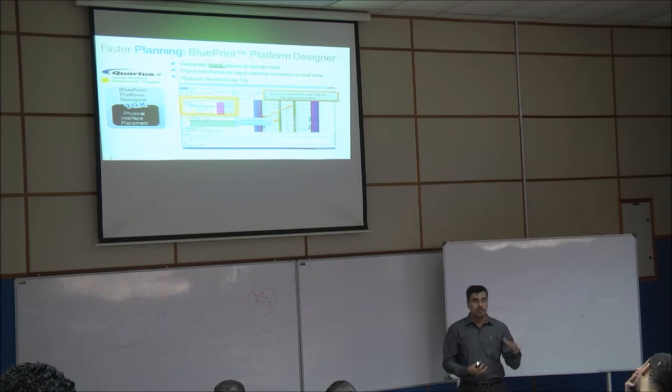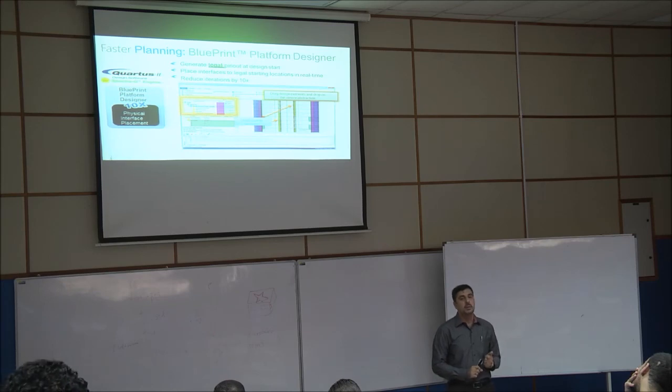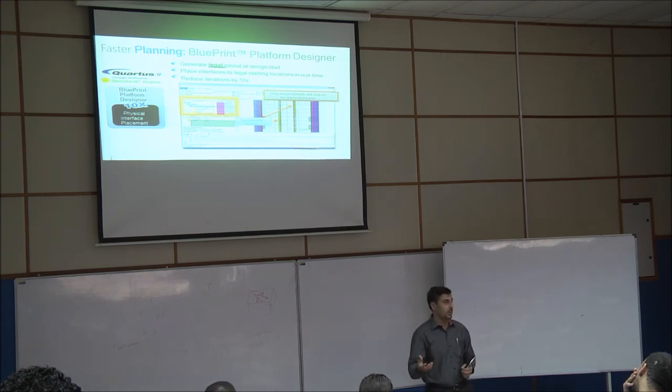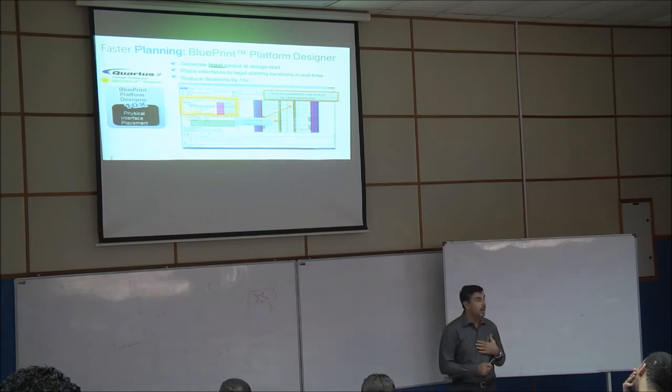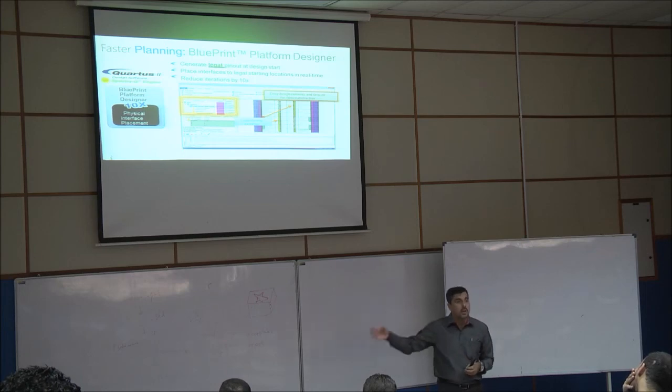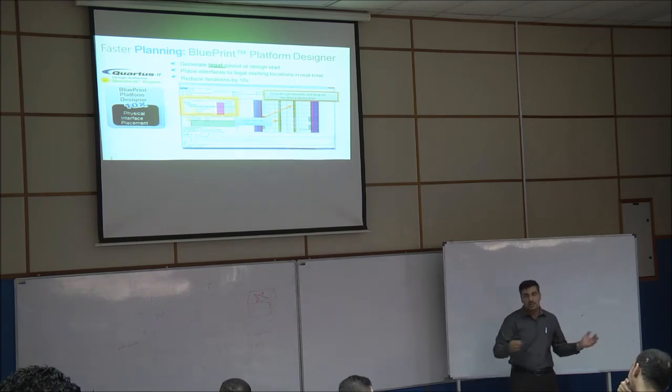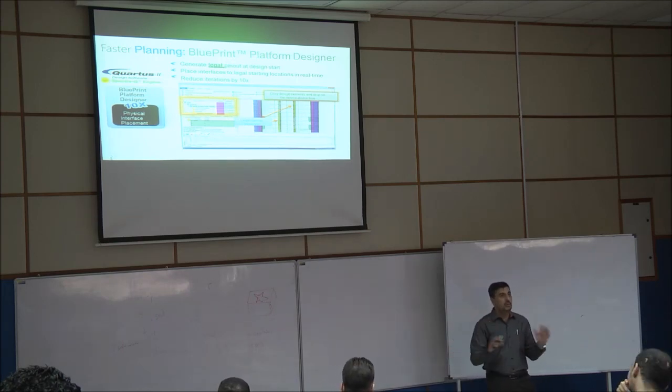Oh, I feel if I put this module beside this module, it becomes faster, right? Clear? But from my experience, because I used floor plan before, in my PhD, even though I worked 20 years in this field, I tried to make it logically arranged by myself. But when I compile, at the end, I didn't get any extra time saving. That means the time done by the compiler is still better than mine. Clear? Why? Because the algorithm they use is very efficient. Sometimes when you have a bulk design, yes, it is very difficult to do that.